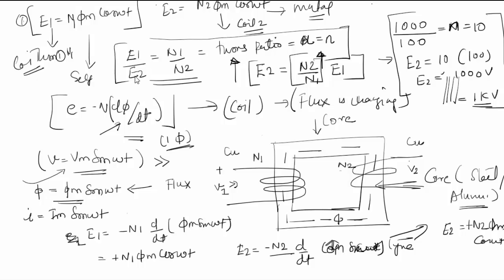And if you look at the equation of the EMF induced, there is something additional here which comes as a result of the differentiation: an omega will be added here, and again an omega here. So it can be said from this figure that the transformation ratio, E1 upon E2 equal to N1 upon N2 equal to A, is for an ideal transformer.